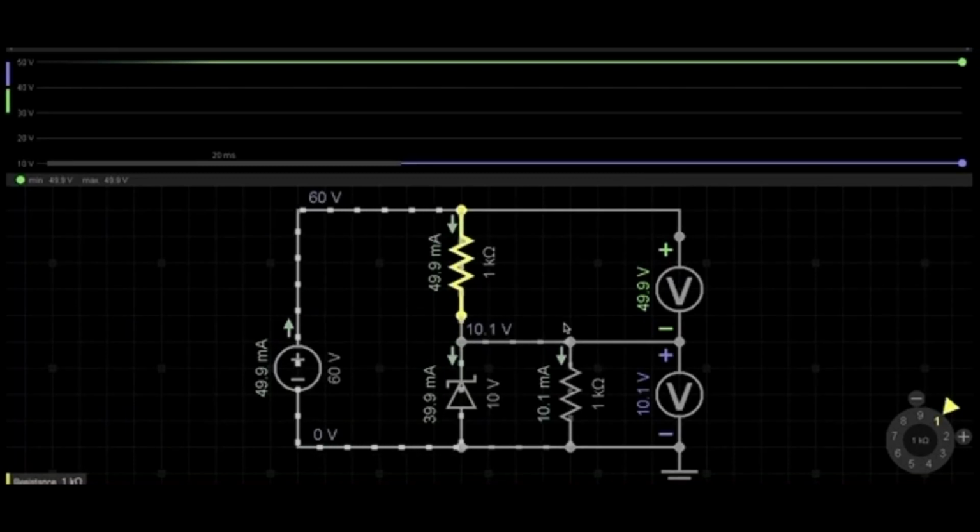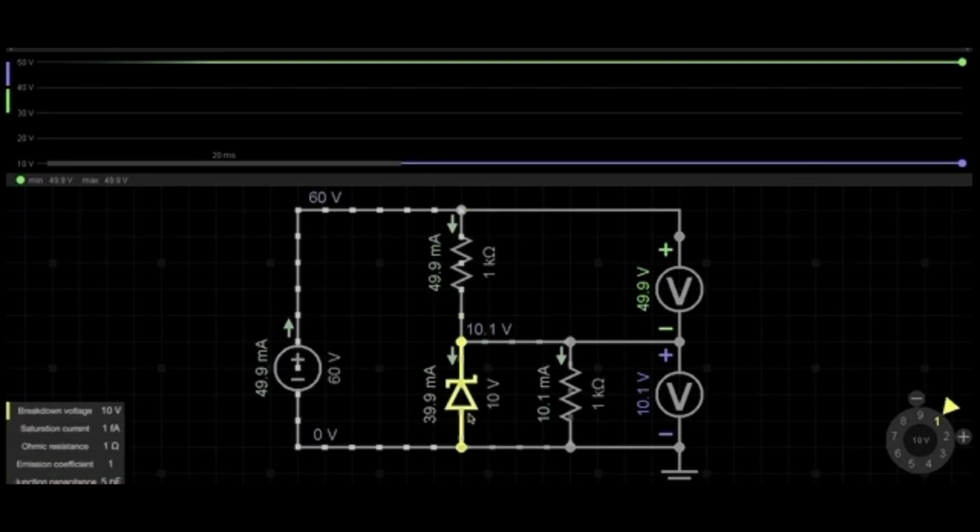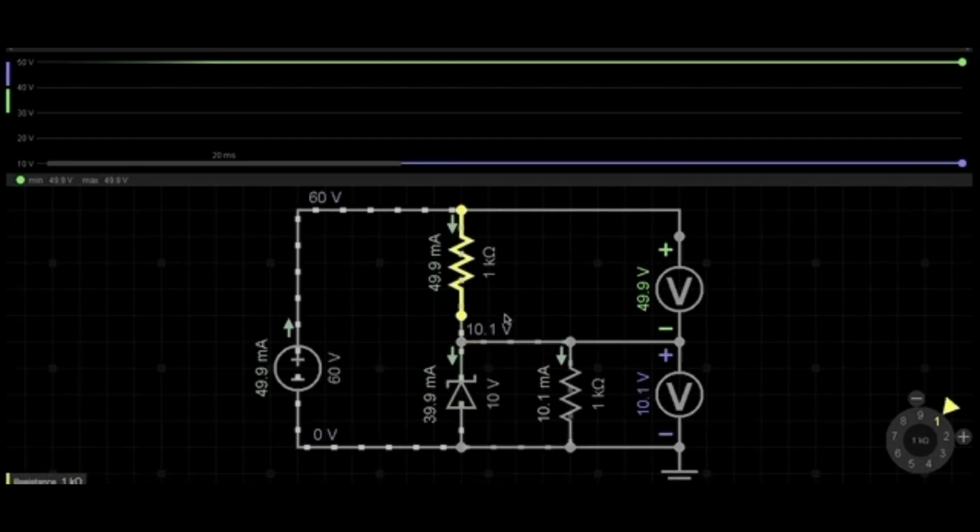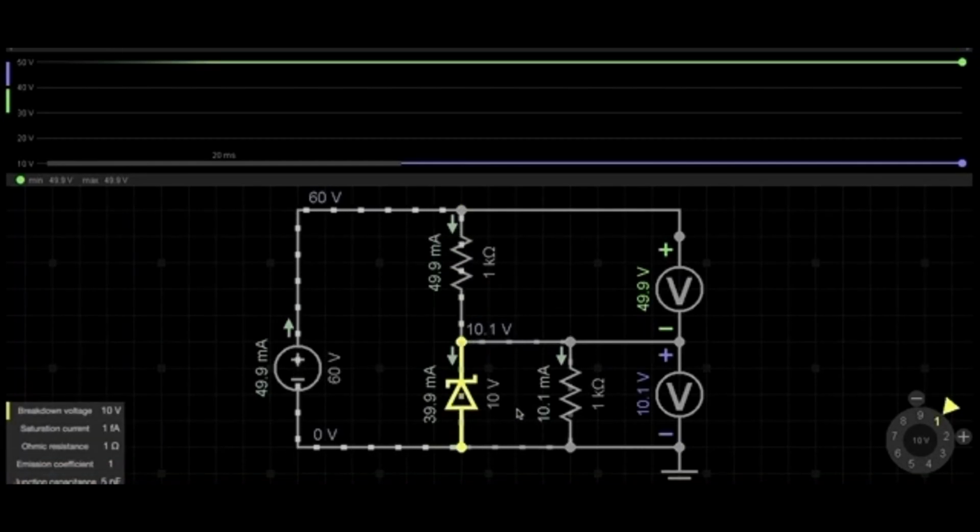It's not a power saving circuit, but still we have an advantage of regulation or stabilization. So the remaining power is actually dissipated as heat, but that's fine. Here we are getting an advantage of regulation and stabilization. More regulation circuits are there in power electronics, where you can use thyristors and advanced switches in order to control the voltage. Here this is a basic circuit, that's why it is becoming a power consuming circuit.